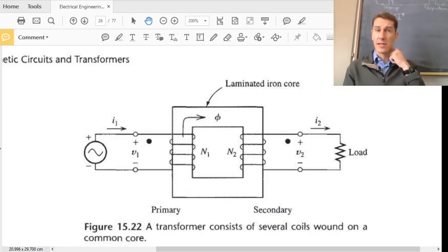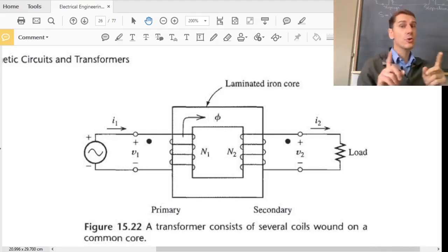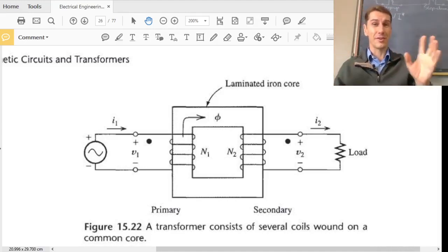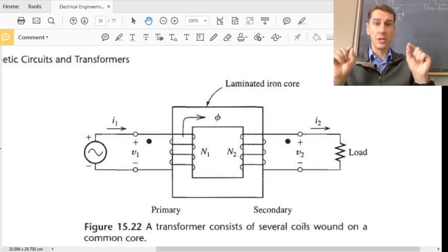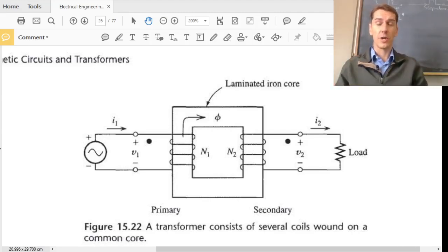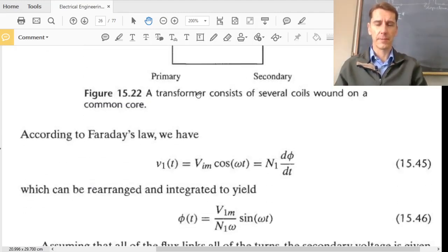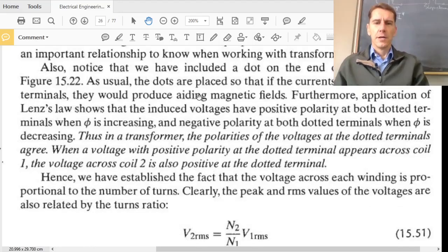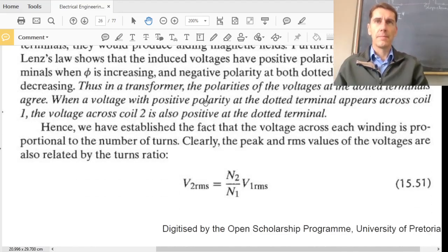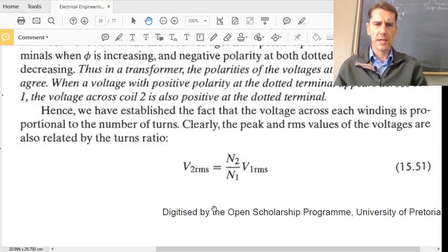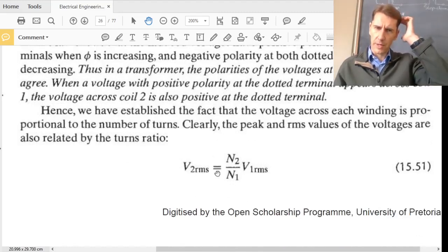All right, so my third years have a practical in the second semester, where they really look at 3-phase transformers. They have to take 3 single ones like these, hook them up as a 3-phase transformer, and if you hook the wrong terminals to both sides, you need to know where the dots are, otherwise you're going to get terrible voltages. So that's all that the dot convention says, and it gives you the ratio again in RMS.